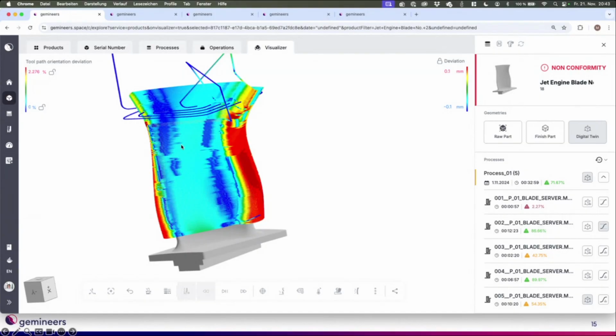Sure. What our customers are doing is, they use our software to analyze the program with air cuts, or to connect it to a virtual machine as well, and to also see, okay, how does the program behave when we look into it with our software. It makes sense when you have high material costs like Inconel, titanium. Before you waste, I don't know, 20,000 US dollars on material, I think you have the time to run the machine without a part on it.